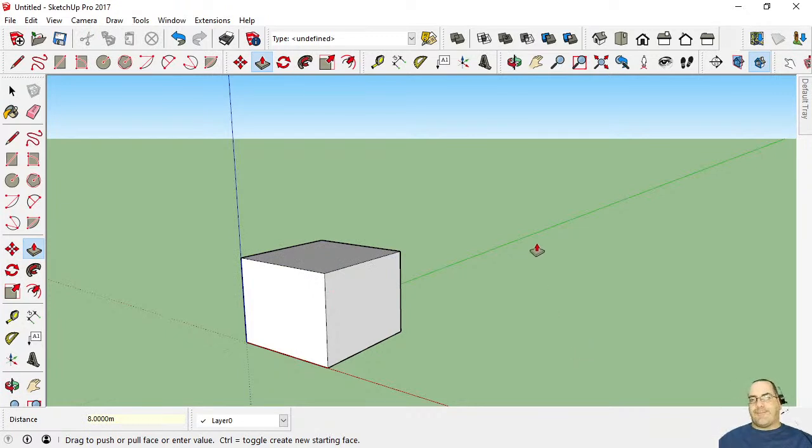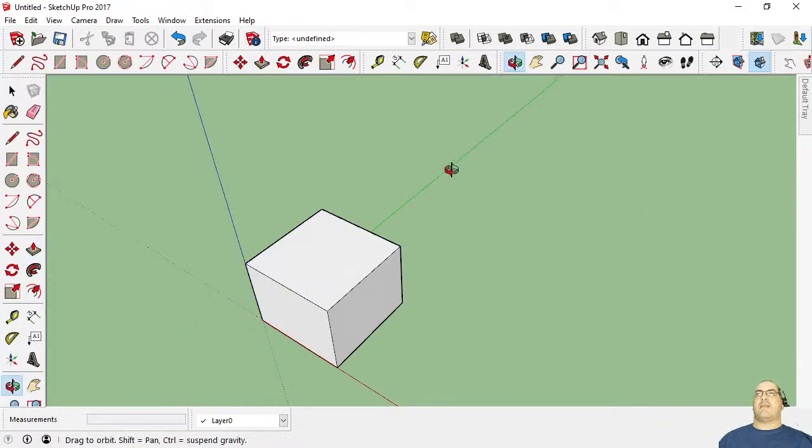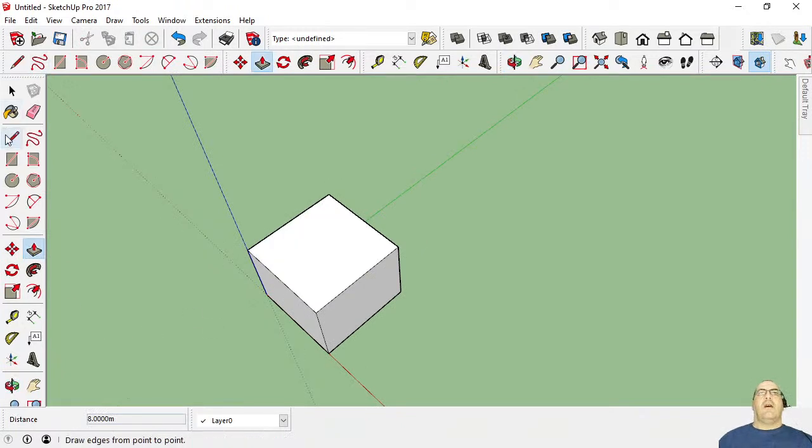Now, as I was saying about midlines and things like that, well, first of all, if we use our middle button and push down, we'll find that we get instant access to our orbit tool. That's the quick way of doing it. So we're on about midlines. There's the midpoint on that edge, and that goes straight across to the midpoint on the other edge. And you know that it's perfectly aligned as well because it's green, which shows that it's aligned with the axis.